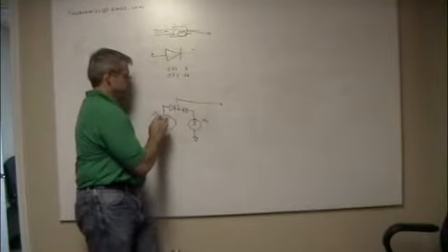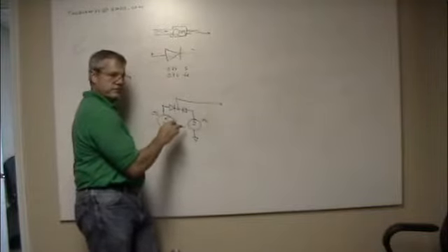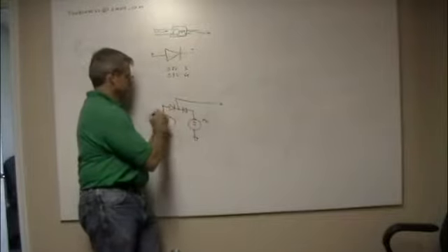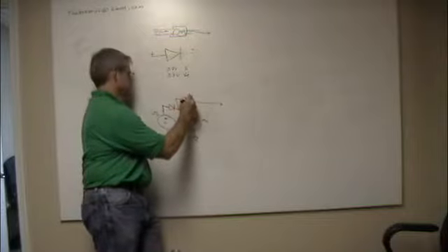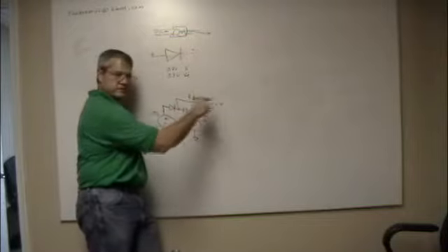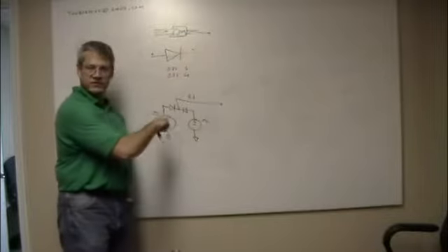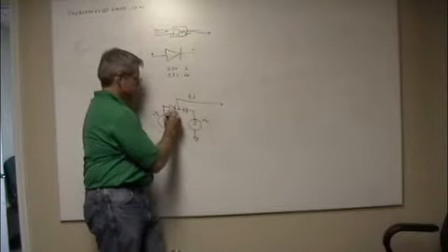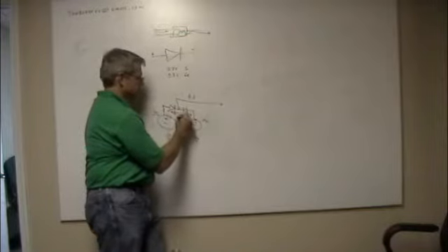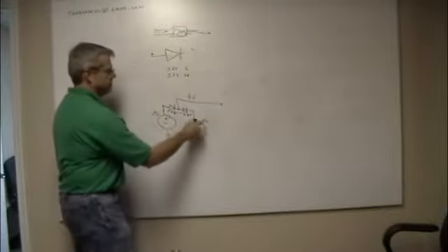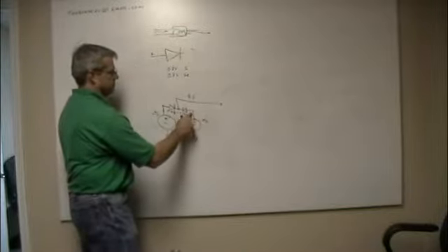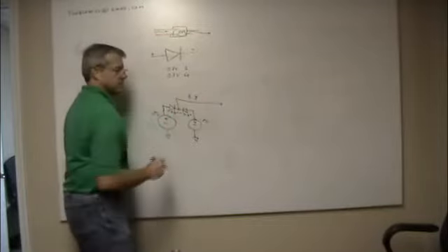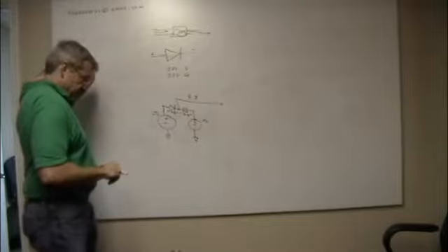This voltage will be the higher of the two. So if this is 5.1 volts and that's 5 volts, this is going to be 4.4 volts coming out. Because you got to subtract that 0.7, right? So current flows this way. So 5 minus 0.7, so I have 4.3, fine. You said 5.1. Yeah, I said one's 5.1, but I've got 5 written down, so I'll stick with that.